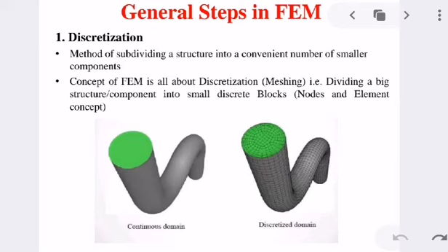So we can say that with a finer mesh, the solution accuracy will be better. You can see a continuous domain in the left side figure and discretized domain, that is meshed domain, in the right side figure. The concept of FEM is all about discretization, dividing a big structure into small discrete blocks,